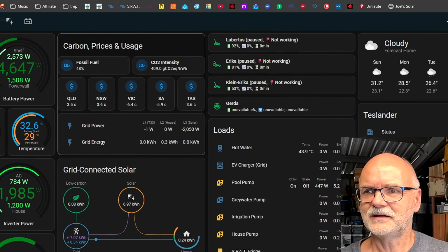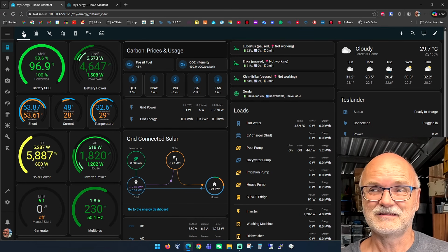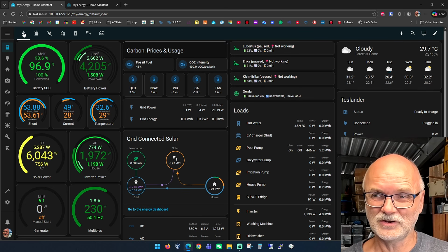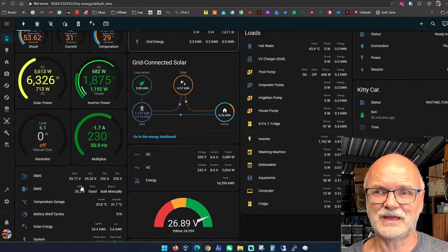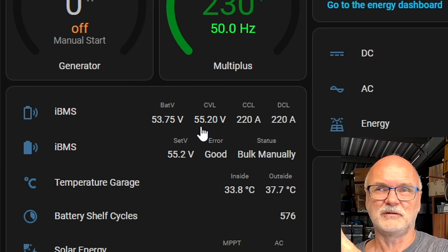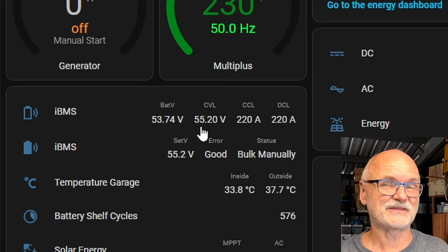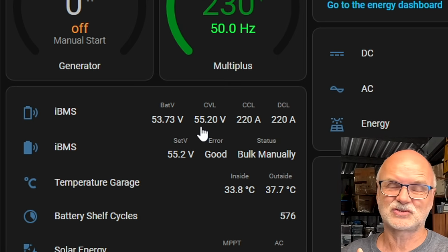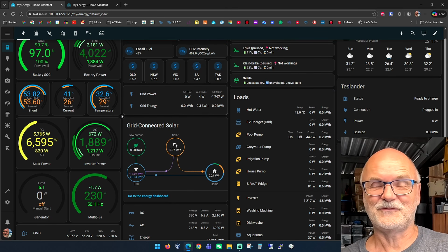Yeah, I think this concludes the whole journey through my Home Assistant dashboards I use for monitoring the battery solar energy system. Except for this automation to change the charge voltage limit at the moment because of the circuit breaker limitation, I don't use any automation to handle the power system. This has all been done by the Victron system. So if Home Assistant fails for whatever reason, it doesn't affect the actual power, battery and solar system. It just keeps running.